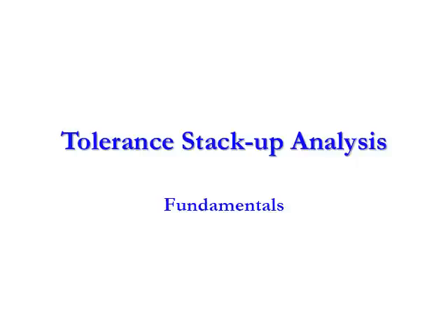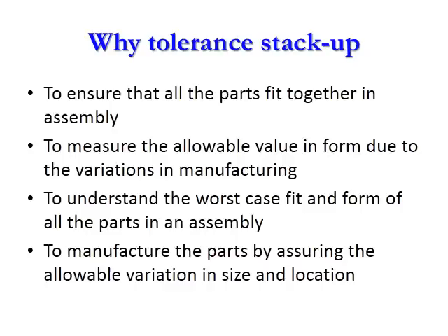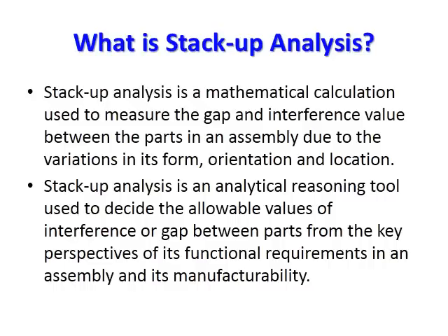Tolerance stackup analysis fundamentals. Why tolerance stackup analysis? To ensure that all the parts fit together in assembly. To measure the allowable value in form due to the variations in manufacturing. To understand the worst case fit and form of the parts in an assembly. To manufacture the parts by assuring the allowable variation in size and location.